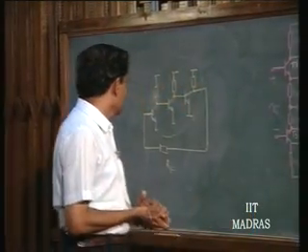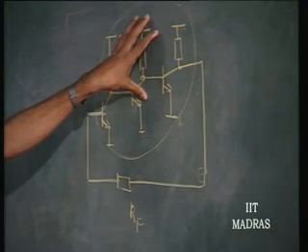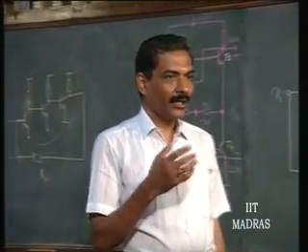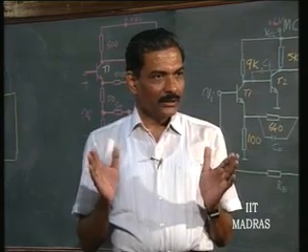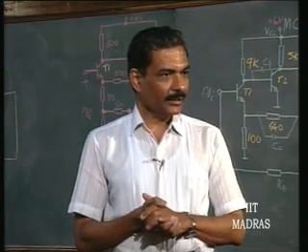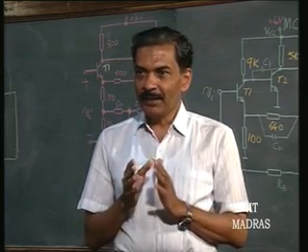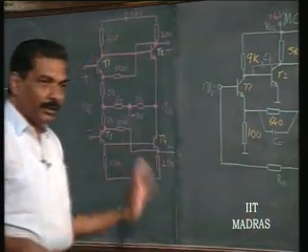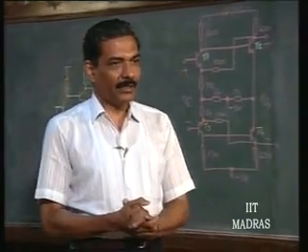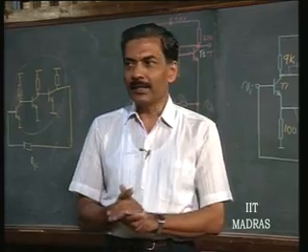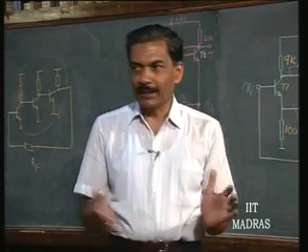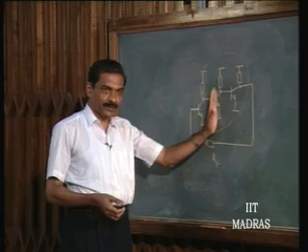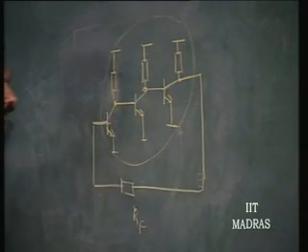Okay. So, a method of analysis is simple, use Y parameters, and therefore, the resulting configuration is going to turn itself into a current controlled voltage source, CCVS, ideal CCVS. Okay. The method of analysis is using Y parameters, and the modified parameters are the Z parameters. Okay. And the forward transfer parameter of importance is Z21, and that is nothing but minus RF in this case. Okay. So, all those methods that we have adopted when we discuss single stage structure is valid here also. So, I am not going to discuss this.